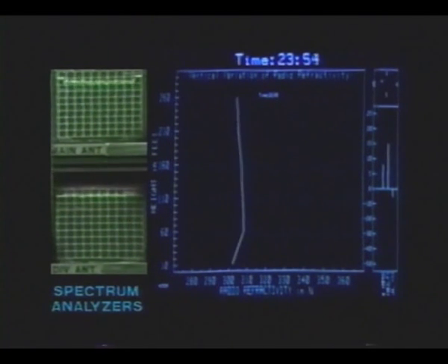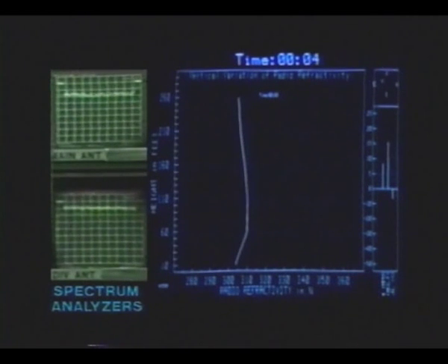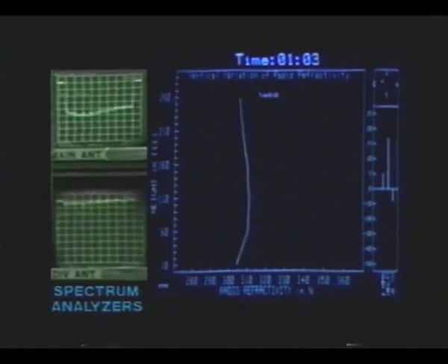During the time between midnight April 26th and 1 a.m. April 27th, the temperature gradient begins to build, but the humidity gradient is very small. This condition results in a 15 to 18 dB flat fade for the main and diversity receivers. Between 1 and 2 a.m., the main and diversity receivers experience a 25 and 12 dB flat fade respectively.